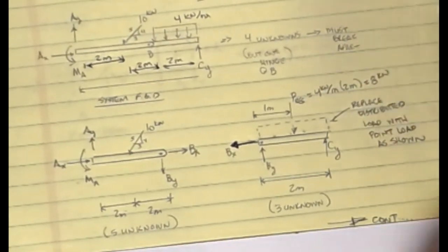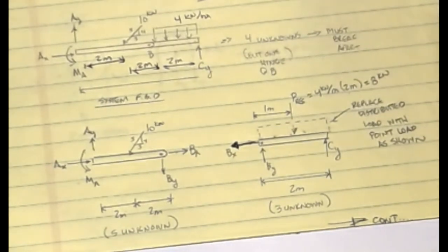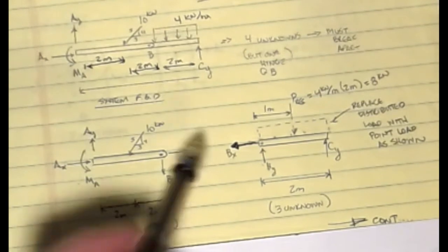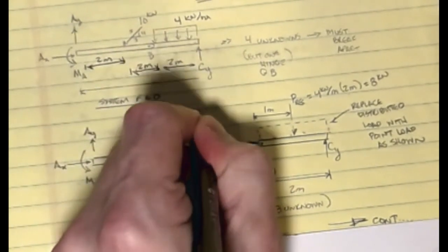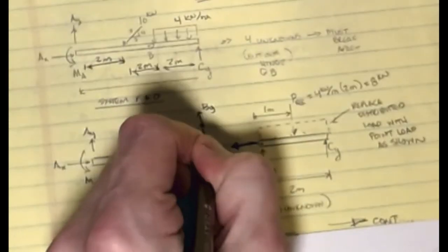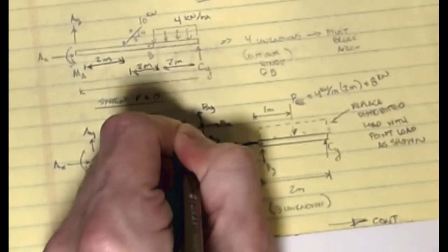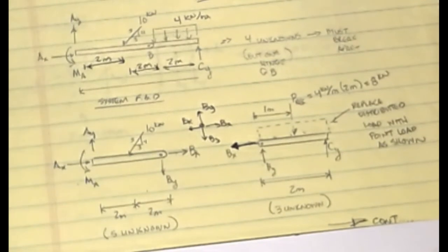Now, one of the challenges in this particular technique is that I now have my two free body diagrams drawn, and again, our hinge is at equilibrium. So if I did this, this would be BY, and then the opposite is BY, and then I do BX, and the opposite is BX. Clearly that's an equilibrium. That's the effect of this member and this member acting on that pin.